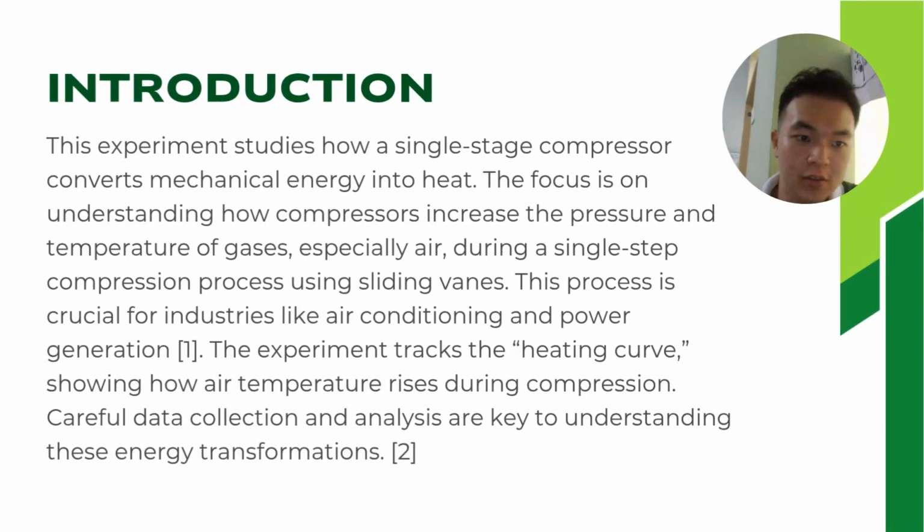So for the introduction, this experiment studies how a single stage compressor converts mechanical energy into heat. The focus is on understanding how compressors increase the pressure and temperature of gas, especially air, during a single step compression process using sliding vanes. This process is crucial for industries like air conditioning and power generation. The experiment tracks the heating curve, showing how air temperature rises during compression. Careful data collection and analysis are key to understanding this energy transformation.